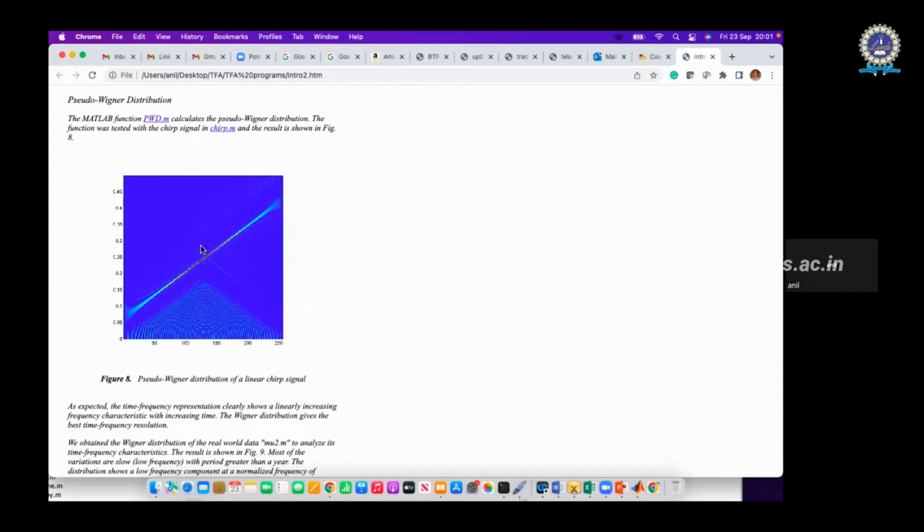But what I'm trying to say is, for example, I take wavelet. It is best for images. It is not best for speech. Similarly, you take short-term Fourier transform. It is best for speech. It won't be best for images. Okay, so it is not that one technique will work for all problems. I cannot do all kinds of signal analysis using one transform. It won't work because I have different techniques.